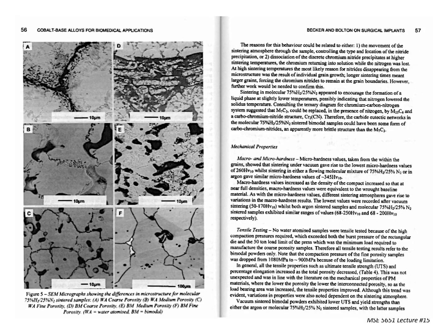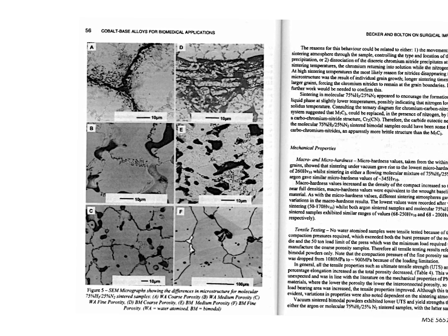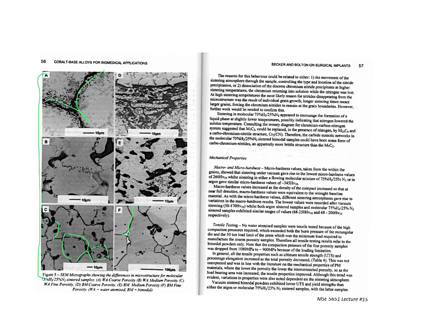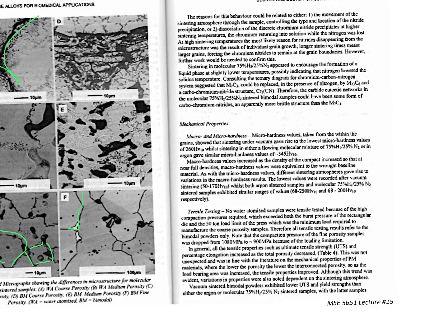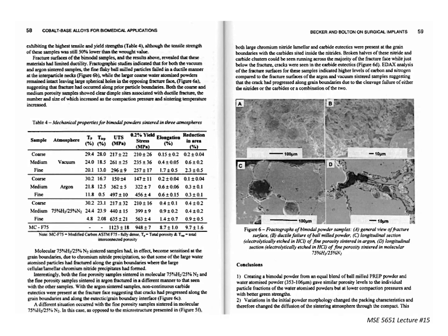All right, so hopefully that's pretty clear. These are also some SEMs showing you, these are all the same scale bar, but we have very, very different grain sizes. Really large here and relatively small here. Carbides on the grain boundaries in some cases, not always, but in some cases they're sitting where they should be. And you can just look through this and get an idea of the struggles they went through to get these things to give them the properties they were looking for.